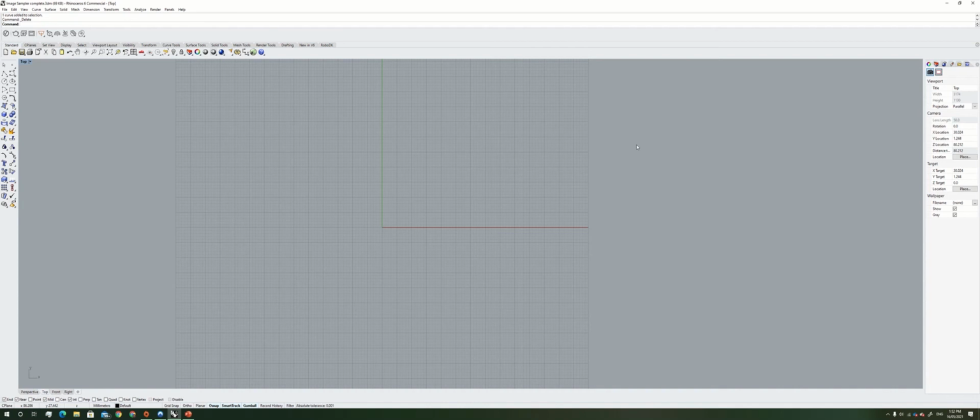Hi there, in this tutorial of Urban Informatics, we'll be looking at image sampling in the Grasshopper plugin for Rhino. Image sampling is basically creating a geometry or an object that mimics the style of a selected image based on its colors. To begin, we'll first start off by creating a rectangle in Rhino.